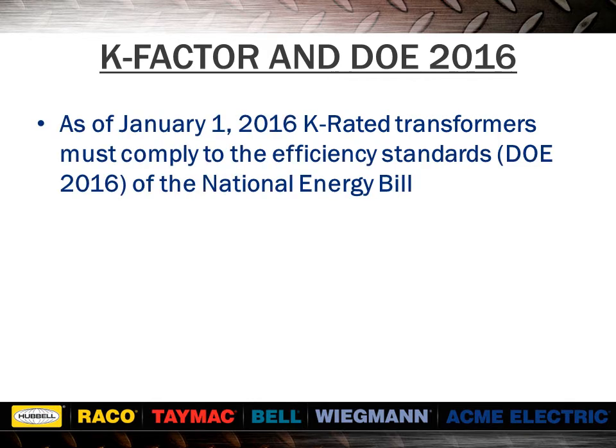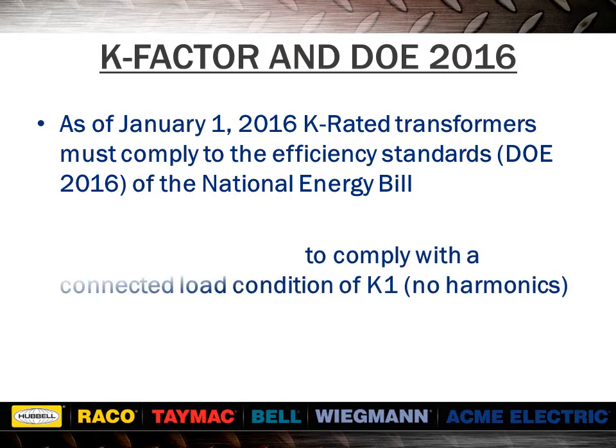As of January 1st, 2016, K-rated transformers must comply to the efficiency standards, DOE 2016, of the National Energy Bill. They are only required to comply with a connected load condition of K1, no harmonics.